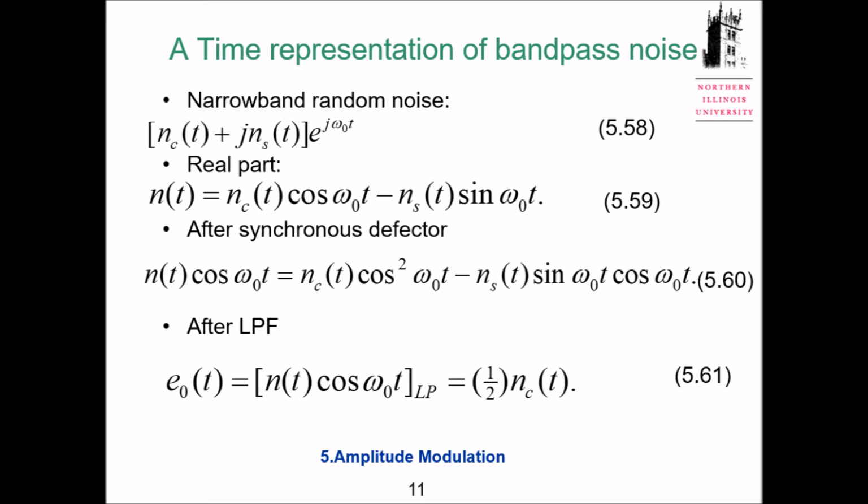Okay, so here we talk about noise. Remember, in chapter 4 we talked about noise. So here we view noise as random noise. It has real parts and imaginary parts. Here e^(jω0t) will make our noise narrowband, like we modulate my noise around carrier ω0. This one will be the same as my ωc. So noise will operate in the same bandwidth as your signal.